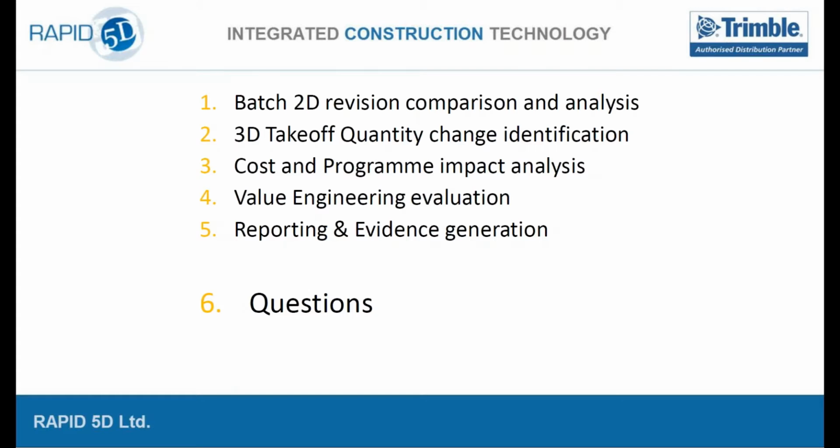okay, these two are the same drawings and here are 2 points that match up on both those drawings. And then Vico is going to fit those two drawings on top of each other, or at least that view, so that you're comparing apples with apples at that point. It's the same view and you can see exactly what's changed. There is usually a section of the BIM execution plan or employer's information requirements that say revisions to drawings should not have their views changing, but obviously at this stage in the game, some people aren't abiding by every aspect of those, or we don't even have that in place.